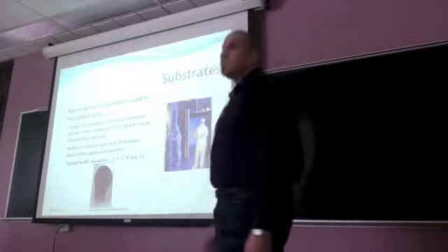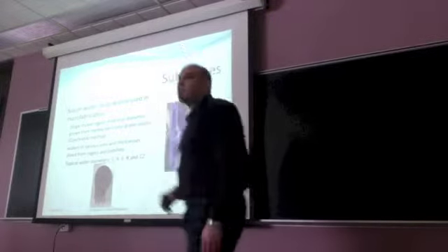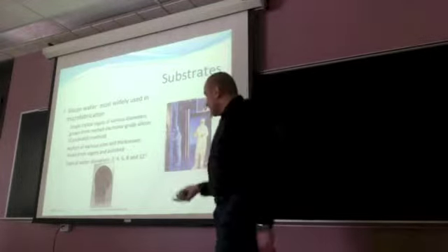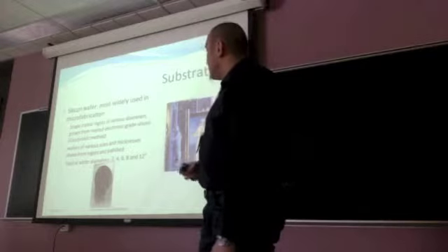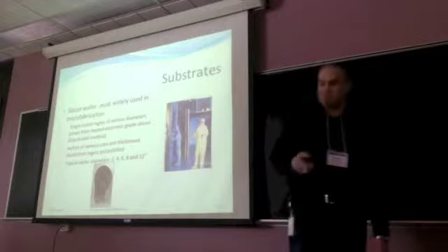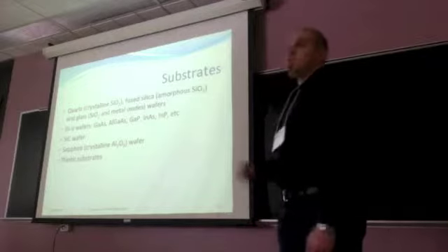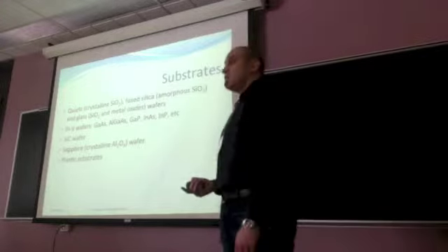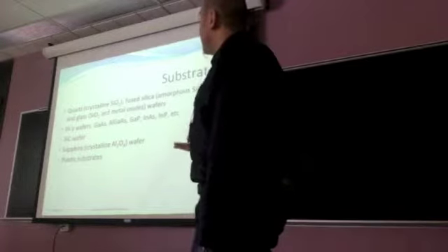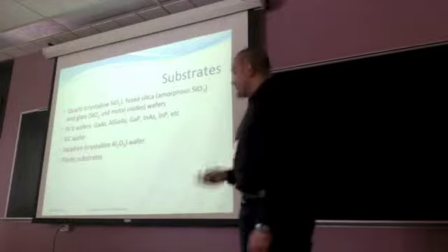These single crystal ingots are sliced and polished to obtain wafers of various sizes and thicknesses. So the typical diameters of wafers are 2, 4, 6, 8, and 12 inches. Other substrates, other materials can also be used depending on the application you need. Quartz, fused silica, and glass wafers are very useful when transparency is needed. They are mainly used for the fabrication of screens and displays.